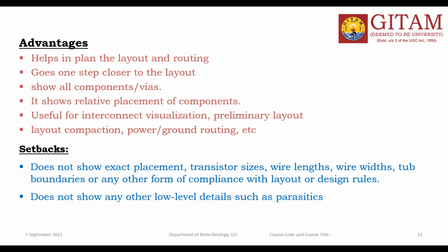The stick diagrams have many advantages, and at the same time they have disadvantages. We already discussed this in the last class. The disadvantages are that it cannot show the geometrical dimensions of each layer. The parasitics produced between the two layers are also missing, as well as the body and well connections.